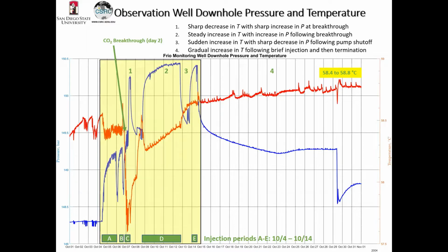It happens very quickly, so you can assume adiabatic, right? There's no heat being transferred to the surroundings. So if you're doing PV work on the fluid and enthalpy is constant, you have a decrease in internal energy, and that could explain the decrease in temperature.